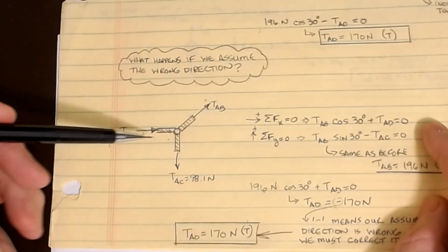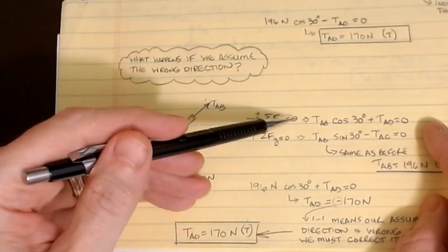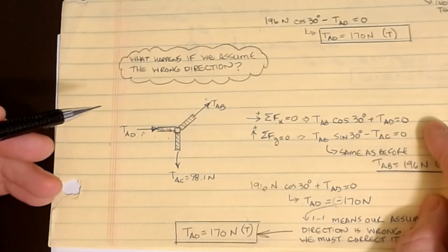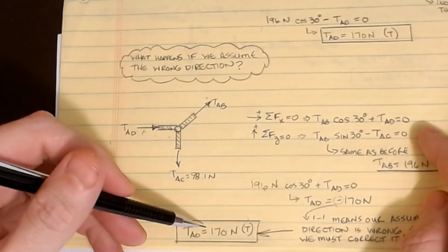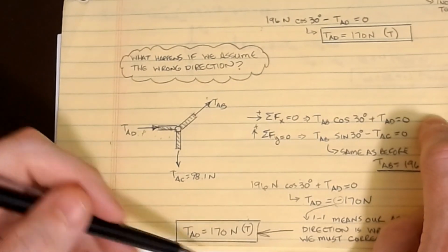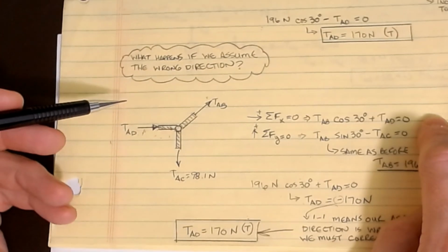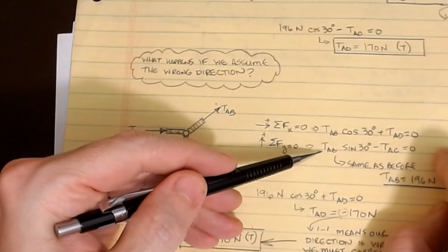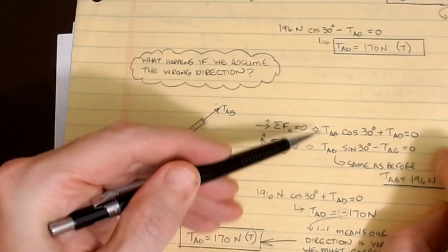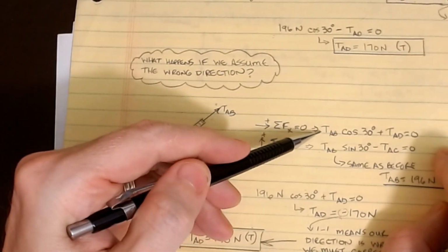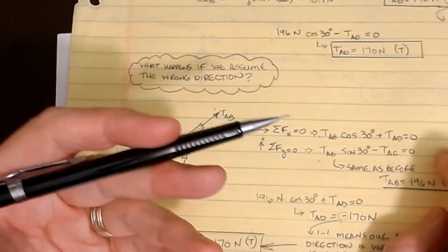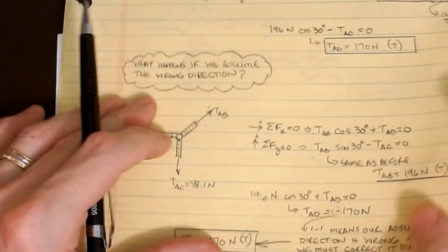So I would argue that you draw your picture once, write your equation once, and then use the value with the signs to fix the equations and the picture, mathematically speaking. That will save you some heartache where you forget to change one equation but you change the other, if there is more than one. Because imagine if you did, in this case, TAB and got it backwards. I would flip the arrow, I would change the sign on this one, but say I forgot to change the other one. Well, then now it's screwed up. The problem just doesn't work out the way that you would hope it would. So anyway, that's kind of the nature of what we're doing.